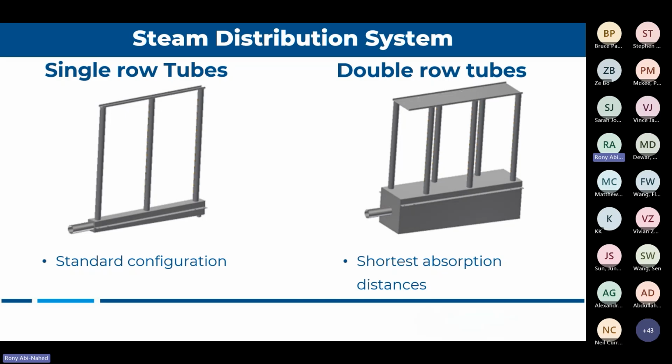So make sure whatever you give as conditions during design is respected on site. Because if it's not, that will change the absorption distance completely. Absorption distance is affected by the speed of the air, by how much outside air is coming, and what the air condition is hitting the grid. So if these conditions change on site, then definitely your absorption distance is changing.